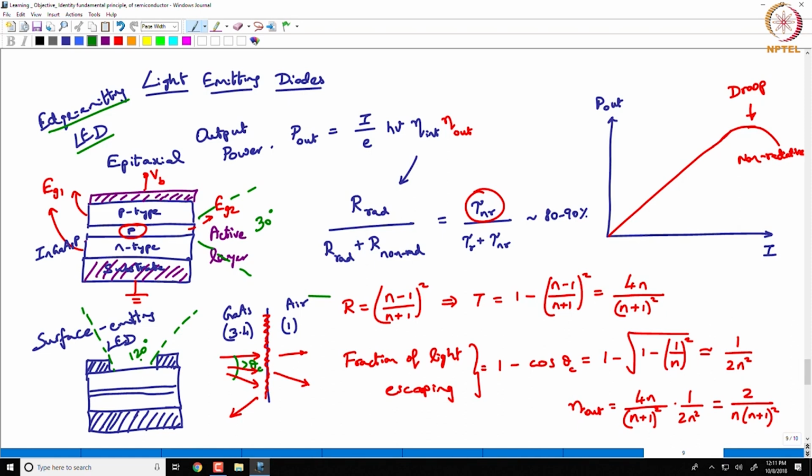So, edge emitting structures are more amenable to coupling into an optical fiber, which may be useful for a lot of applications. We are talking about LED, but we will go ahead and talk about a laser diode. So, in terms of semiconductor laser diodes, those would tend to be the sources for optical communication applications, long distance optical communication applications.